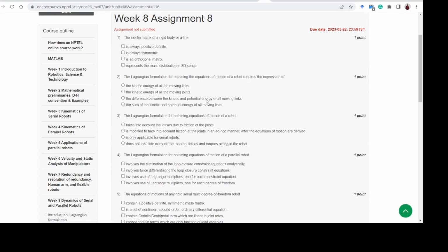One can also do some preliminary theoretical checks. Imagine that in any vector space, with any choice of coordinates, the mass matrix does not appear to be symmetric in the kinetic energy term. It has to be symmetric, because only the symmetric part of any matrix contributes to the kinetic energy. If you take any general matrix M and compute X transpose M X, and decompose M as the sum of symmetric and antisymmetric parts, the antisymmetric part goes to zero, and you are left with X transpose times the symmetric part of M times X. So the mass matrix will always be positive definite and symmetric.